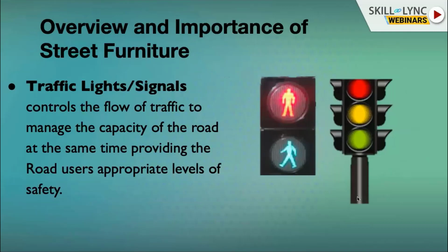These are the traffic lights or traffic signals. These are the equipment which are provided mainly at the junctions in order to control the traffic movement coming from different approach roads. These traffic lights are designed with phasing, and phasing means the time intervals that are provided for each arm's traffic movement. These phasings are not picked randomly, they are arrived upon through careful traffic data analysis to provide a reasonable queue length. It may not be a zero queue length at all times, depending upon the saturation of the junction. The queue length may increase or decrease, and even the phasing may alter to accommodate the capacity of the junction.